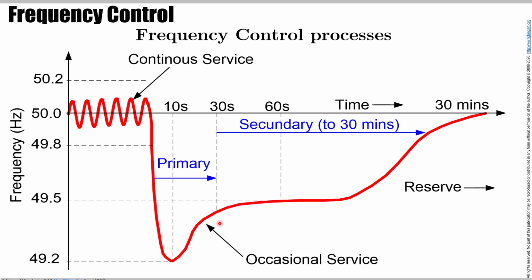And at that moment, if everything was fine and the power system has enough capacity to recover the frequency after the disturbance, the primary controller will try to stop the frequency from falling, and the frequency probably will reach what we call a pseudo steady state frequency, below the nominal frequency.